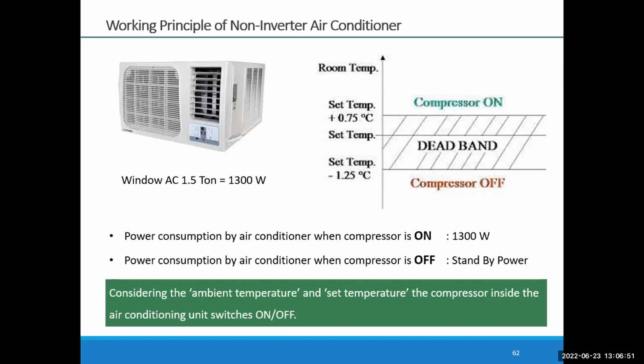And once the vehicle is moving, then you require less energy. But if you have to keep stopping the vehicle and then pushing it again, then you will have to keep using this extra strength. And that's how the compressor looks at it. Every time it starts, it's an extra load. And then you stop and then you start. So you're burning a lot of current because you're asking for what you call a starting current. So what you're aiming for is not to stop, but to actually slow down. And that is why you need the inverter type.